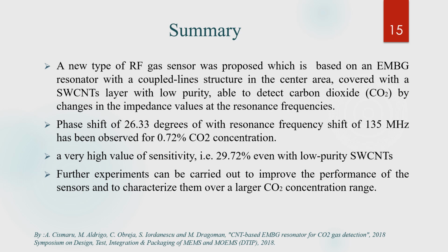A phase shift of 26.33 degrees with a resonance frequency shift of 135 MHz has been observed for CO2 gas of 0.72% concentration, and a very high sensitivity value of 29.72% has been observed even with low purity SWCNTs used. And as mentioned earlier, there is a lot of scope for future experiments to improve the performance of the sensors and to characterize them over a larger carbon dioxide concentration range.